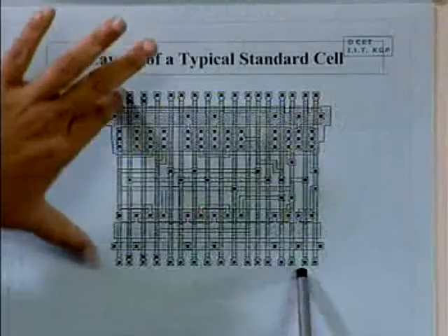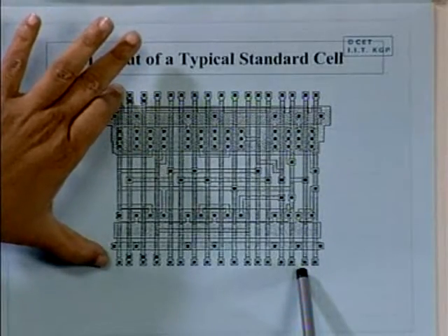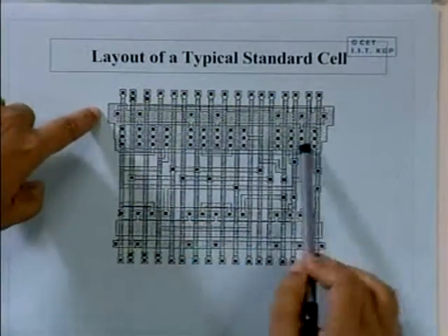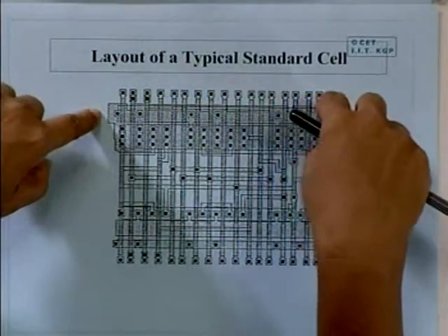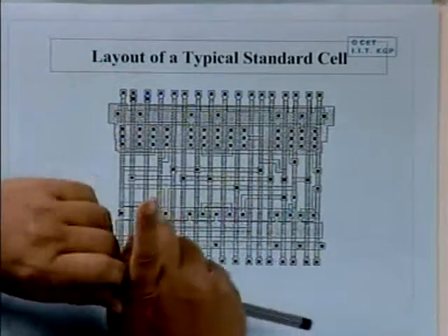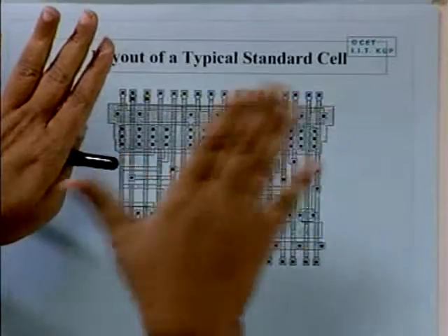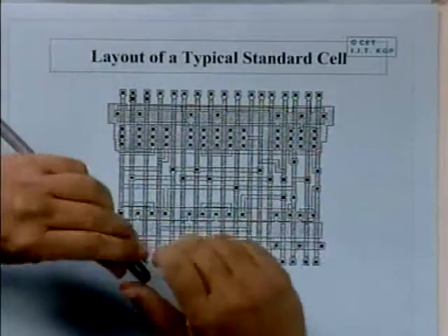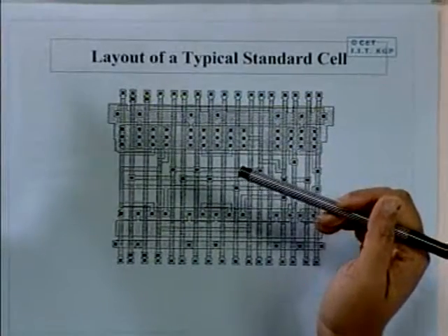The I/O pins, which interface with the outside world, are normally made by columns, and these are rows where the basic cells are placed. The power lines as well as the ground lines run parallel. The NMOS transistors are normally kept nearer the ground lines and the PMOS transistors nearer the power lines. But why, we will read later.